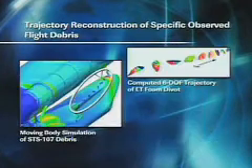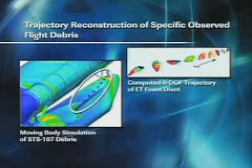In the next chart, the other thing we try to do is take specific debris events where we observe the piece of debris in the flow field, and we try to model and replicate that. On the left is a simulation that the Ames Research Center community did of the STS-114 debris coming off the bipod. That is a CFD solution of both the debris and the vehicle flying, combined in unsteady flow. It's a very sophisticated model. And then we use that to cross-check against simpler models that we use.